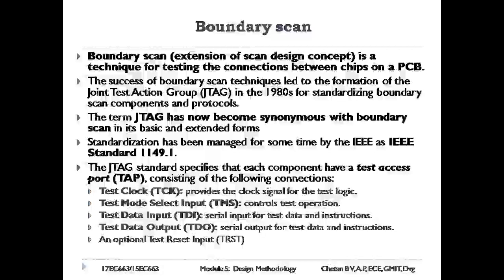The first one is test clock (TCK), which provides the clock signal for the test logic. The second one is test mode select input (TMS), which controls test operation. The third one is test data input (TDI), serial input for test data and instructions. The fourth one is test data output (TDO), serial output for test data and instructions. The last one is an optional test reset input (TRST).